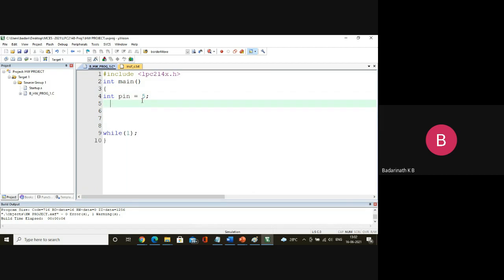That means the pin P0.5 I have to set to the first alternate function. So what do I do? To get that particular bit number, I say 5 into 2. When I say 5 into 2, I get 10. Bit numbers 10 and 11 I'm interested in. First you have to write 00 into those bits, yes or no? How do you write 00 into that?